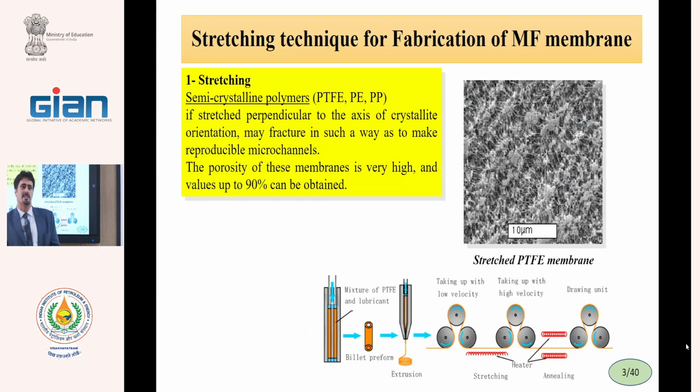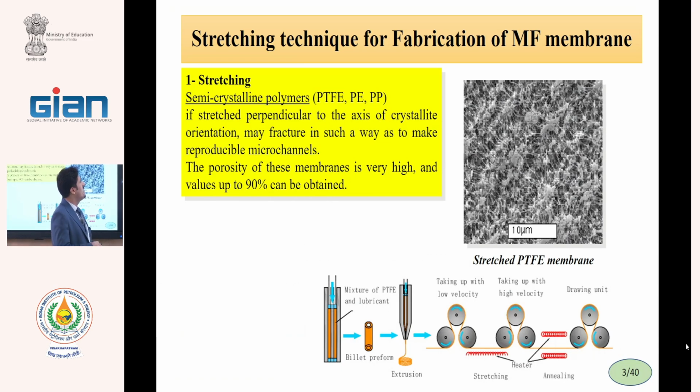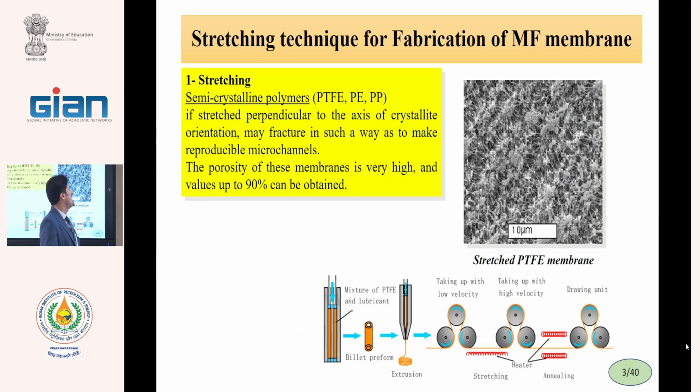The first technique, which is a very old technique, is the stretching technique. In the stretching technique, we use semi-crystalline polymers such as PTFE, polyethylene, polypropylene, and we usually melt them, not dissolve them in solvent.